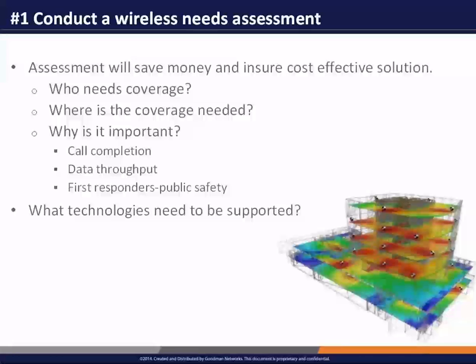first responders. And finally, we need to do an assessment of what technologies need to be supported. And those technologies could include, for example, not just voice, but Wi-Fi related applications and technologies. Again, the new DAS systems have the ability to do some piggybacking of Wi-Fi systems, and in your assessment, it's a great time to understand what's happening with regard to Wi-Fi and the unlicensed frequencies.